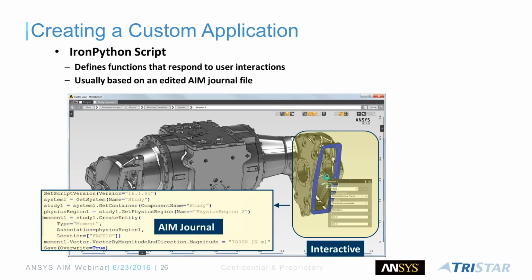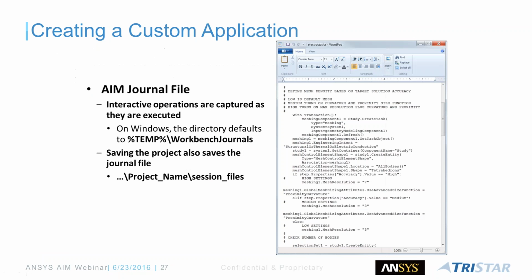So when you start using ANSYS, if you use an existing template and you start applying loads, constraints, etc., ANSYS is saving, right? You see this journal file, it's actually saving all your interactions with the system. All we're doing is saving that as an extension and then loading that as an extension so that all users can use it, right? In fact, you can even edit that if you know some scripting language. Here's an example, right?